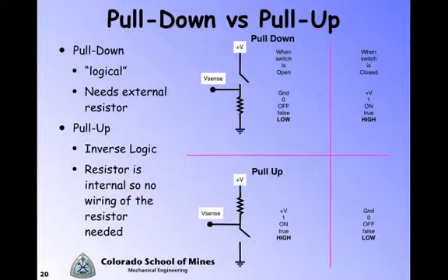If the switch is open, then the potential that's on V-sense is the same as ground. No current is flowing, and so there's no voltage drop across the resistor. Thus, we have a 0 voltage reading. We could say it's off. We could say it's false. And in Arduino speak, we would refer to it as low.